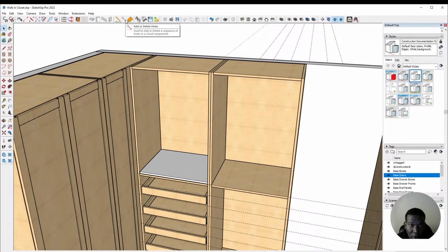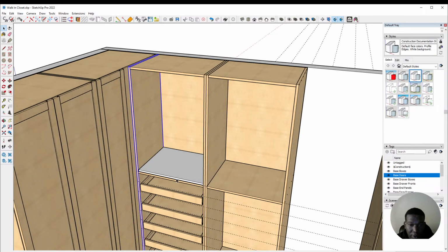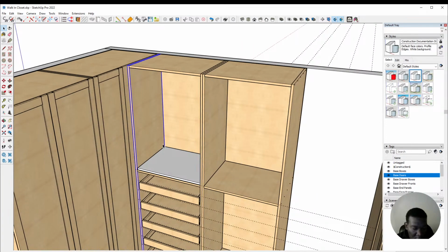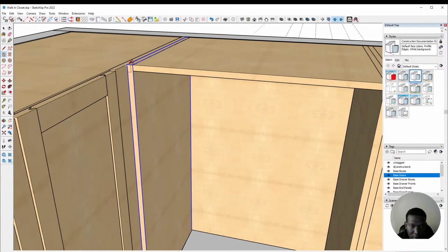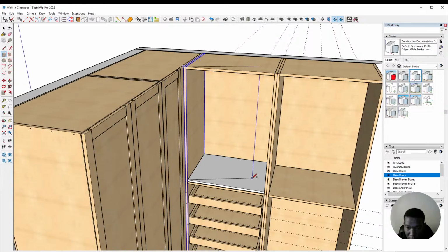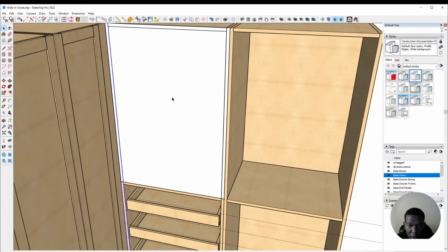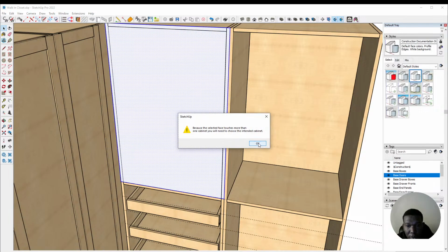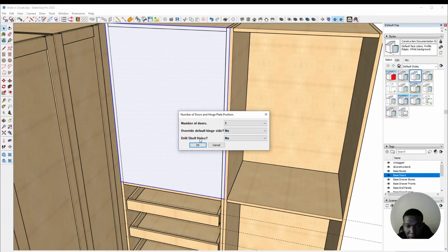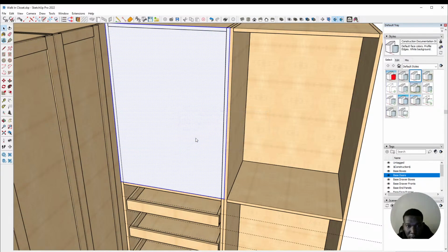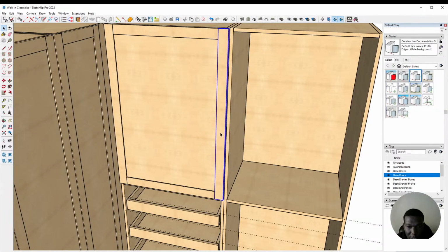So you cannot use this tool to make the holes for the adjustable shelves. And if you have a CNC and want to make those also using a CNC, you have a problem which you can solve by creating a small door, somewhere there, and selecting, then insert a door, okay, yes, no, then reshape holes, yes, you want to drill those ones, okay, done. Then delete the door,